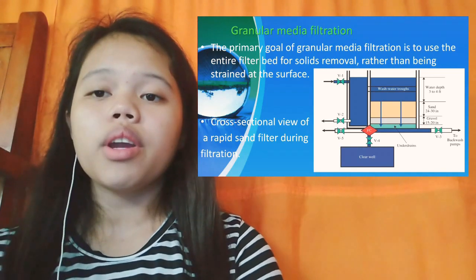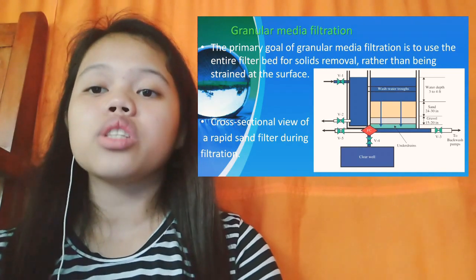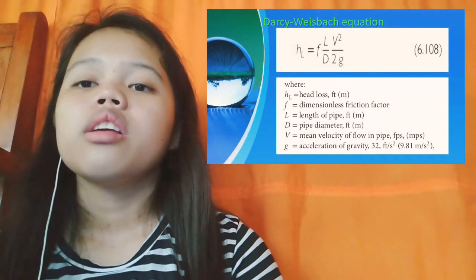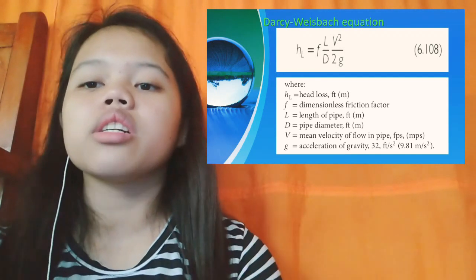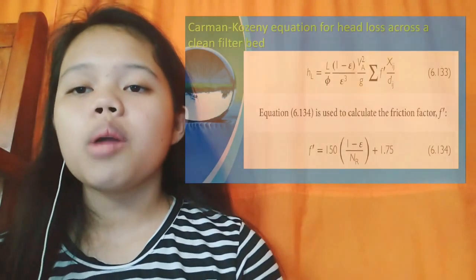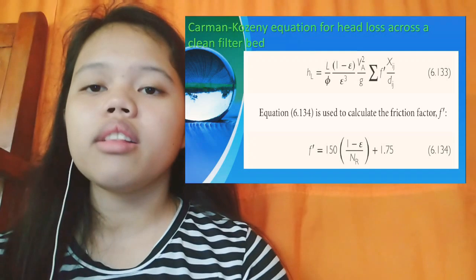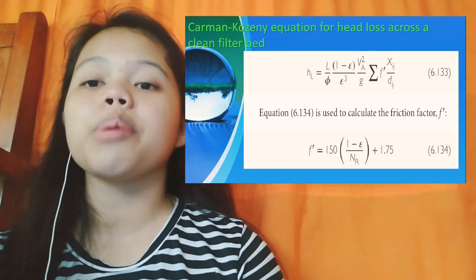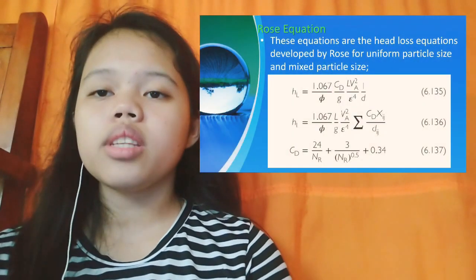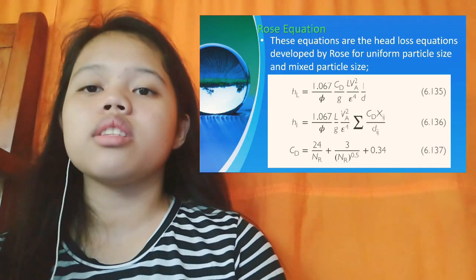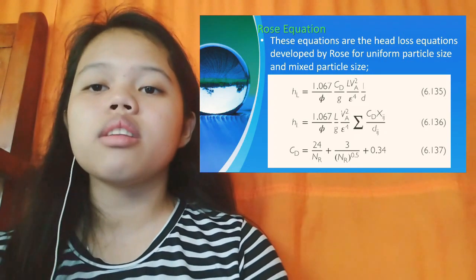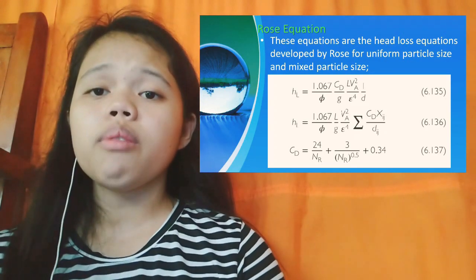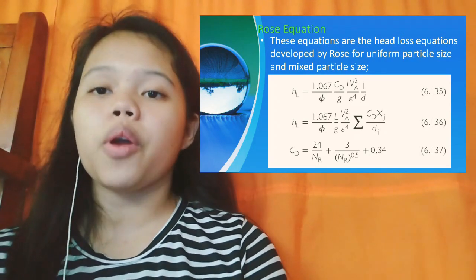Cross-sectional view of a rapid sand filter during filtration. Darcy-Weisbach equation. Kozeny-Carman equation for head loss across a clean filter bed. Rose equation. These equations are the head loss equations developed by Rose for uniform particle size and mixed particle size.